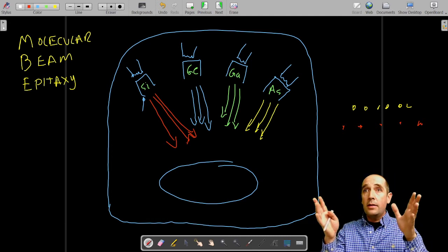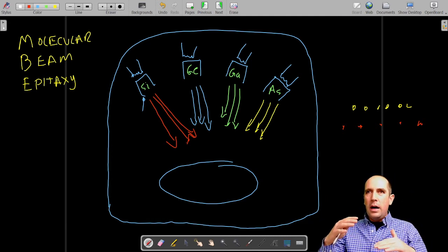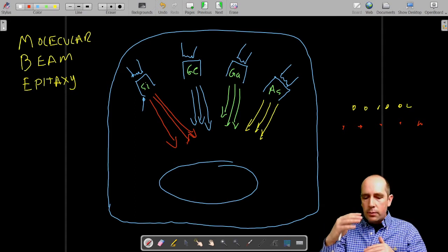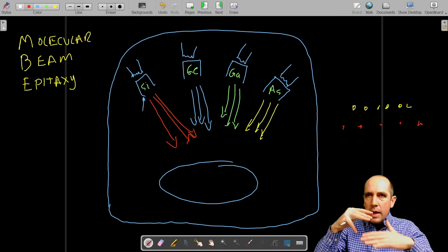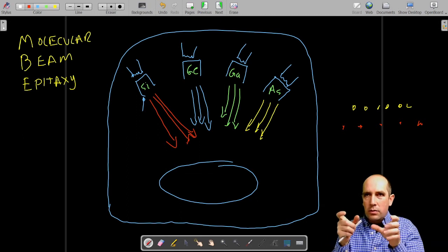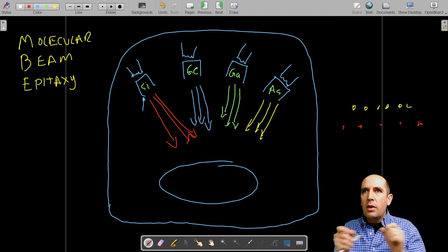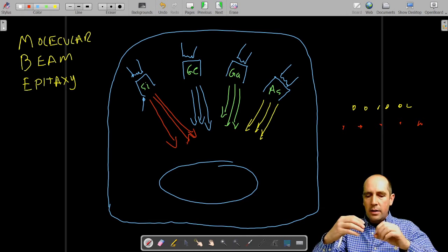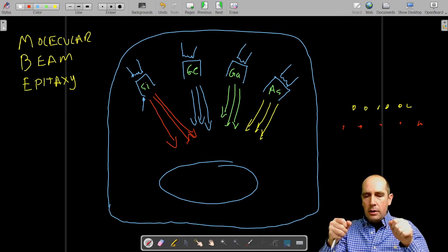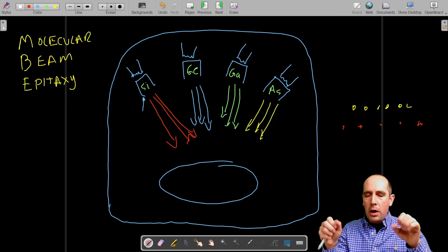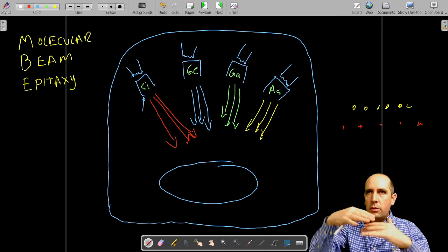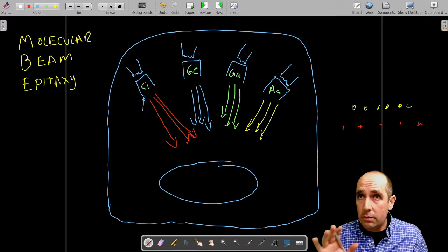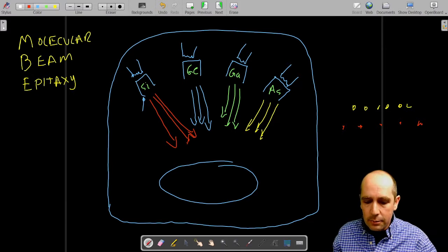So the spacing in the lattice is different, and therefore when you try to grow germanium on top of silicon, this could be hard just because the atoms don't align with each other, because they will be stressed. I mean, the layers near the interface will be either pushed together or far apart, depending on the mismatch between the two lattices. But let's not worry about the lattice mismatch yet.